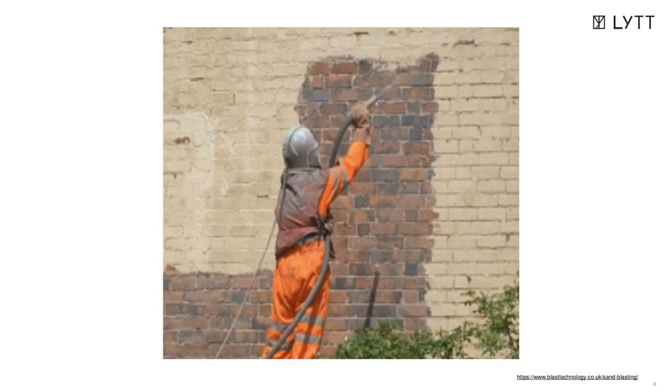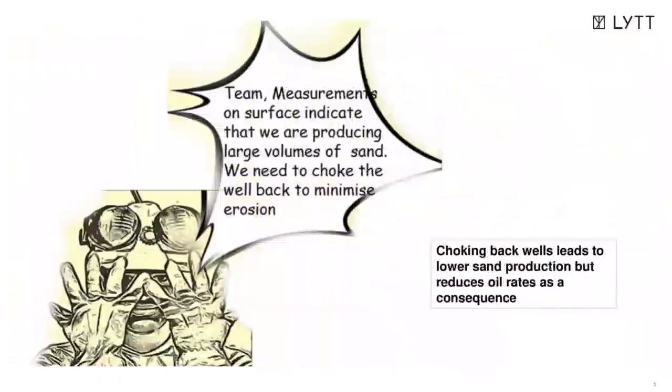If it is established that the well is consistently sanding, they are choked back to minimize sand production and erosion risks. This, however, implies that the well's production performance also gets a hit. This may mean an offshore well that has been set up to produce higher rates of oil eventually may end up producing just a small fraction of what it was supposed to, consequently resulting in pretty significant production losses. Production deferrals can sometimes be as high as 90% of the well's production capacity, making this one of the industry's key technical challenges to solve today.